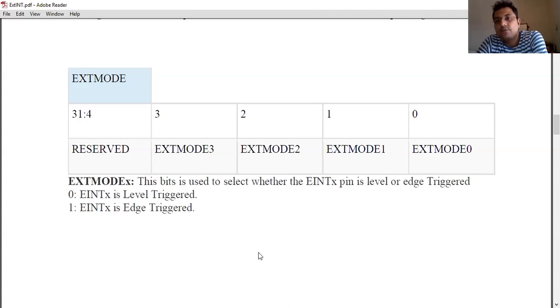Likewise, if you have configured the mode as edge triggered, 2 possibilities are there. Either the signal can rise, so the rising edge may be considered as acceptance or registration of an interrupt, or the falling edge could be taken as an acceptance or acknowledgement of an interrupt.